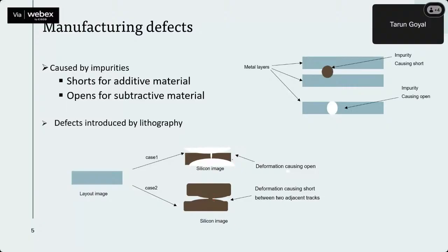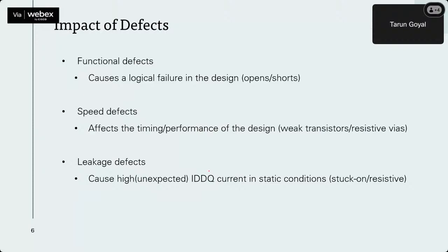These kinds of defects are very normal with respect to the technology node, until the technology process matures, and TSMC and all these manufacturers keep improving their process. If these defects are there for particular metal layers, they start improving based on the feedback from DFT and all the tech nodes, whatever testing we are doing. All of these have to be corrected and detected. That's part of the job of DFT, ensuring we are detecting defects and not shipping them to customers. Now I'm starting on the impact of defects.